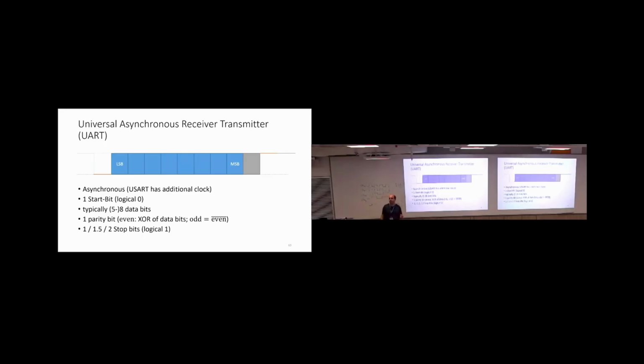No, you start with the transmission. So time goes from left to right. The first bit that is transmitted is the LSB. Yeah? So why do you do this? Because we will later see also for adders and multipliers, if you first transmit the LSB, you can immediately start processing. If you first transmit the MSB, most of the time you have to wait.